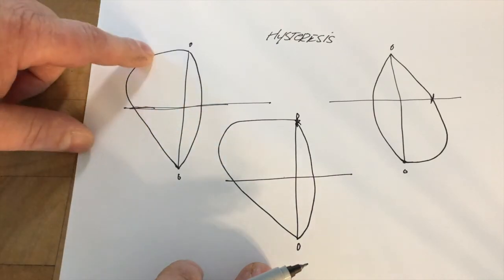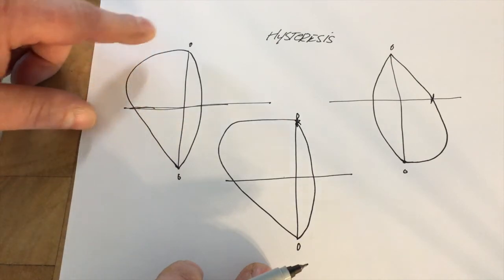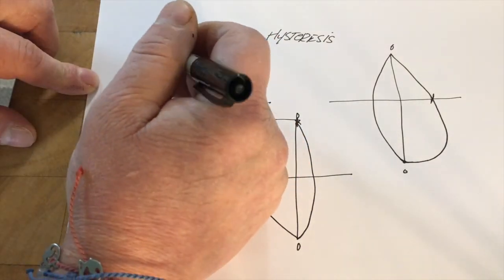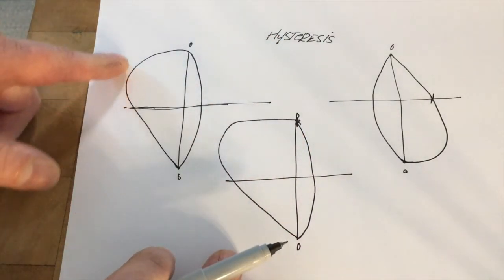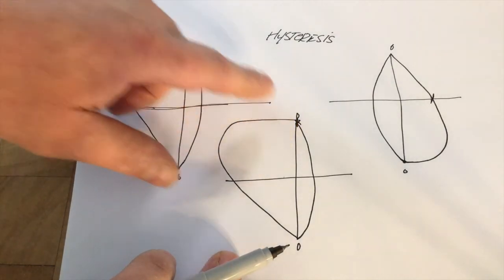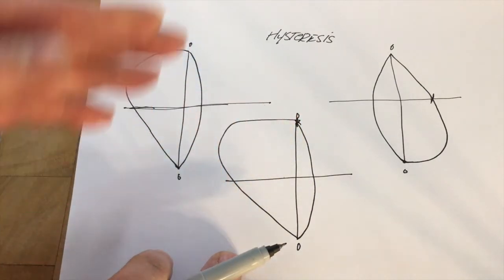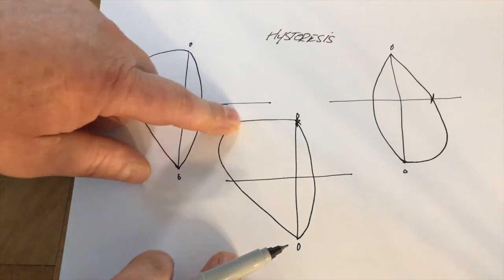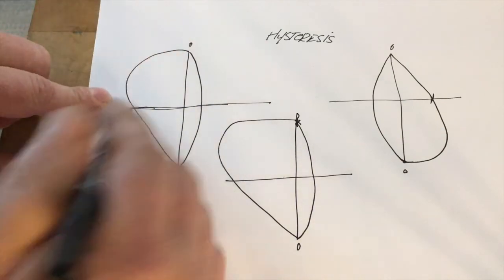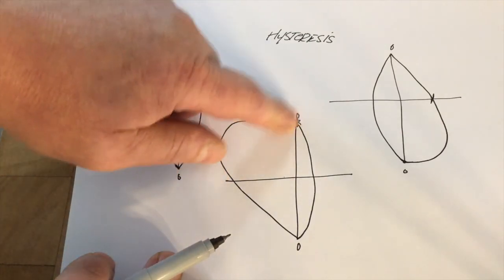Typical right front. This is another deal, probably like the right front where you're locking down. This has probably got a little bit more bleed because it's a little bit more rounded here. As it starts to close, the bleed's a little bigger. If you do it all with bleed and the bleed is real small, it'll wait till the shock really slows down, then snaps closed. So it gets into that bleed range where everything can stop. Like I said, this is probably a little bit more bleed because of the angle on this, and this is probably a little bit less bleed because it snaps closed faster.